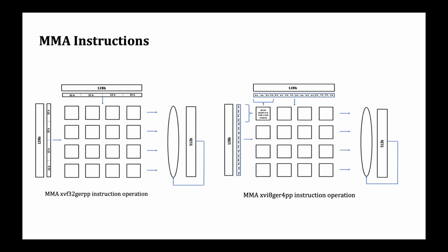So basically, we are not expanding our register file size. If you know x86 and you look at Power, Power supports vectorization with a vector length of 128-bit. That means it can support 4 single precision operations in a single instruction, or 2 double precision. And x86 architecture is more like AVX-512, so it supports 512-bit. From an external point of view, it might look like 512 is bigger than 128. But with this innovation, even with a 128-bit architecture, we are able to generate the same level of compute capability as 512-bit, without complicating the hardware too much.